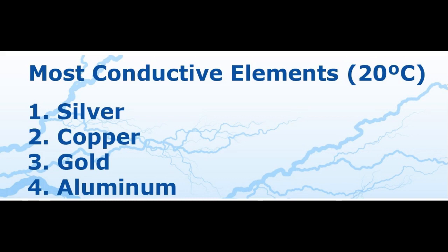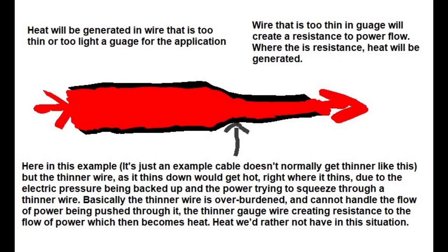Now on to a rather important aspect of this tutorial related to DC wire gauge. In a word, resistance. I'll explain. Resistance is quite an issue in the low voltage DC world. If you're trying to push any amount of power down a wire that is too thin, then you will experience resistance, just like a tube that is too thin for the amount of water you might want to flow out the end. Too thin an electrical wire in a DC circuit reduces the amount of current flow.